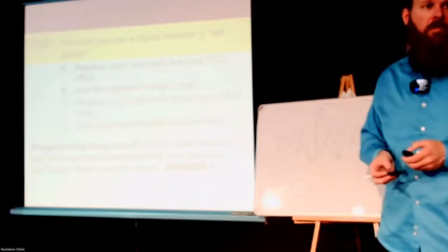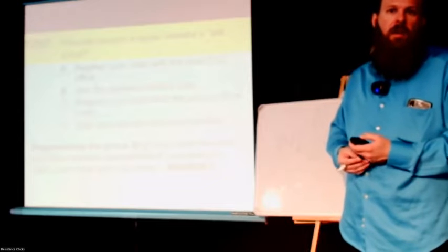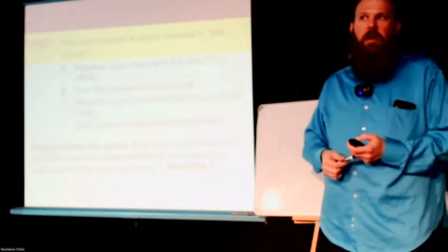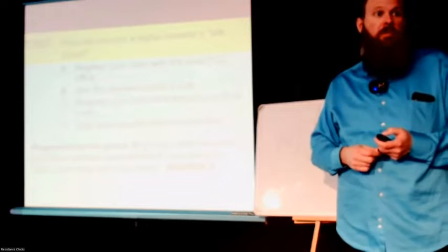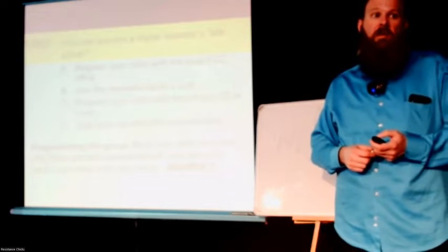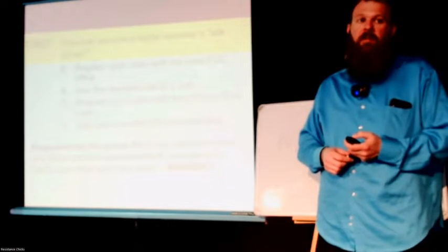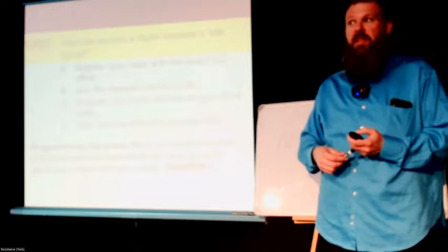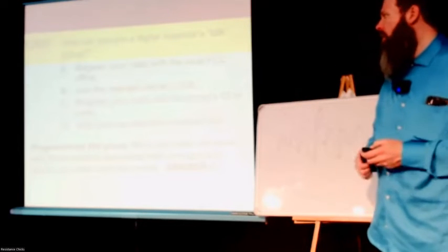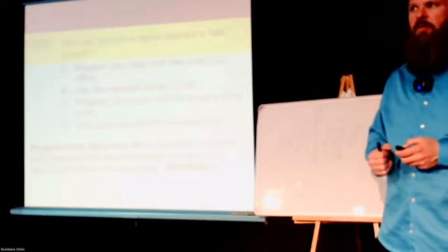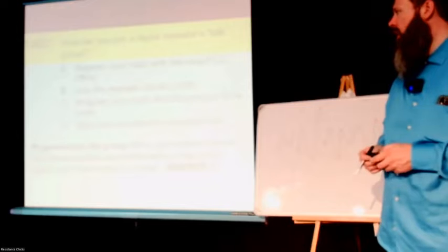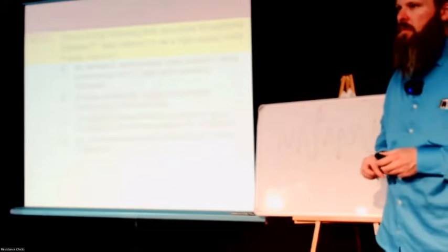Yep. And more than one group use the same repeater? If it's a DMR repeater, yes, because you could operate in time slot 1 or time slot 2. And then, of course, you could ultimately just share where when somebody else is transmitting, you can't, but between their transmissions, you could transmit. So that would allow you to share, but it generally doesn't work very well that way, unless you're all in the same group together. Then you're taking turns. So you can only have 2 groups per repeater.